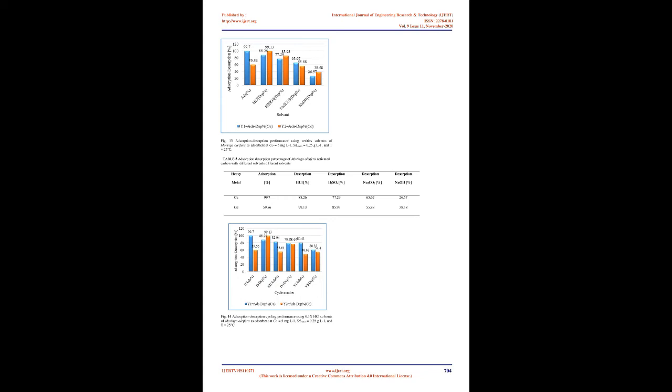After reaching 0.025 g of adsorbent dosage, the adsorption process also reached the equilibrium state. The removal percentage of pollutant from aqueous solution improved with increasing dosage. This can be attributed to the availability of active sites on the adsorbent for complexation of heavy metals. Further increasing the adsorbent dose showed no significant improvement in removal. This may be due to reaching equilibrium between bound adsorbate and unadsorbed adsorbate in the adsorption process.